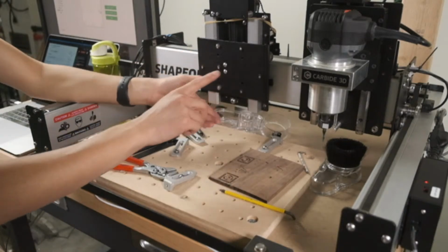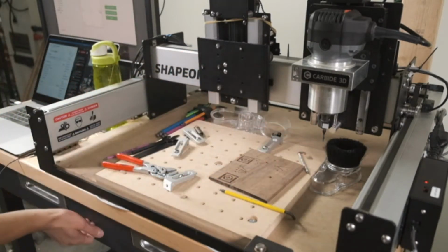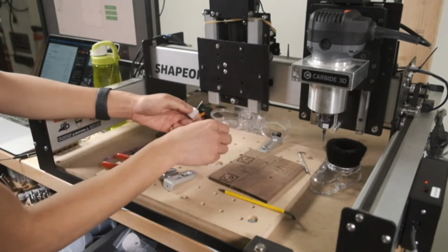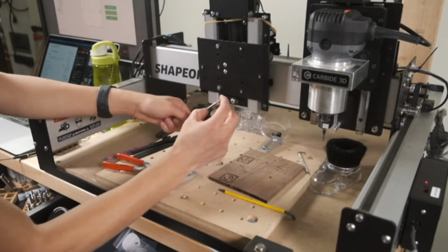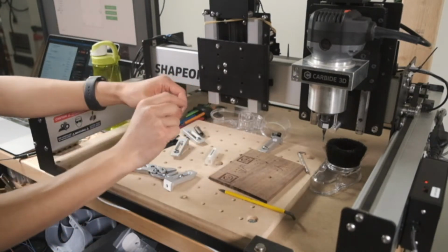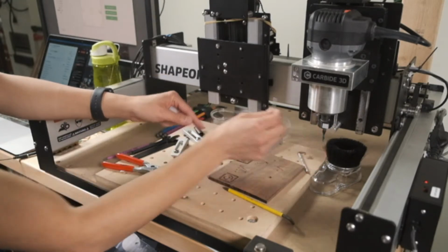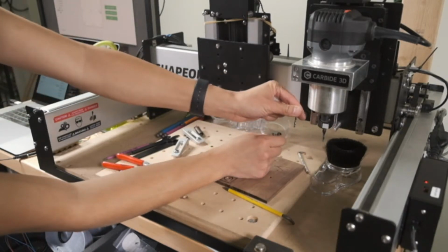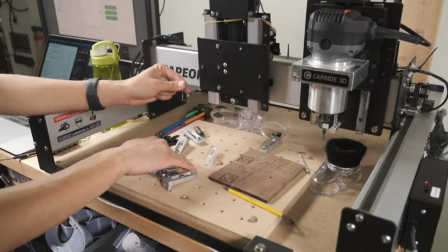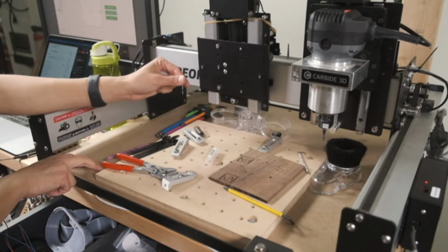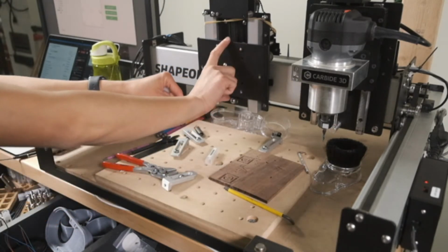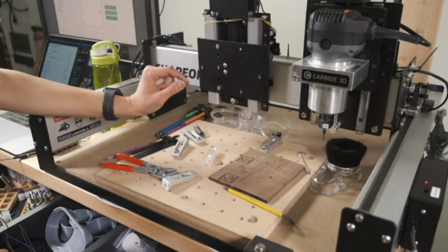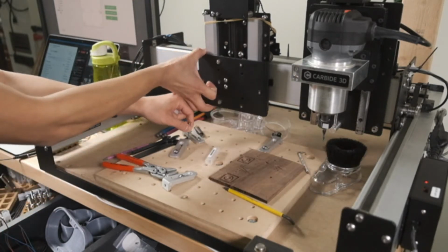With a lot of people using smaller tools, like let's say our 102, 101, the regular 1/8" tooling we sell is pretty short. It's 1.5 inches. And if you insert that into a router, it's only going to stick out about this far. And so to have a short end mill reach the wasteboard, or even if you don't have a wasteboard, the baseboard, this has to come down pretty darn far. So if you're cutting at the surface with a short tool, check to make sure you're not running off the rails.